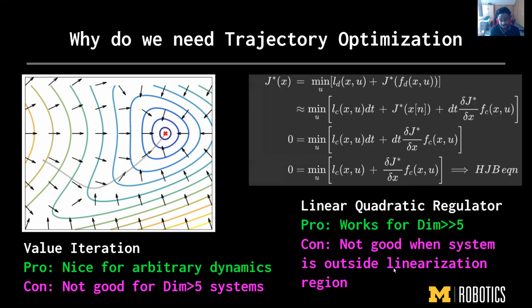For instance, if you want to plan a trajectory from some initial state to some goal state, say you're a quadrotor and want an optimal trajectory from a start state to a goal state, the trajectory is going to be made up of multiple states. And so you could end up having to linearize at each point, which is actually what's performed by iterative LQR. You could get that to work, but LQR in its current form will not be able to work for such a task that requires a longer trajectory.